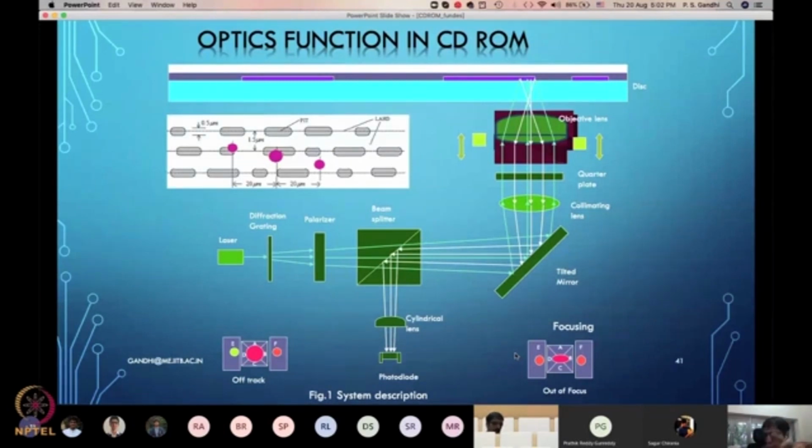Okay, this we often need to do in the practical world, when we are even configuring a simple motor and encoder system. Okay, what is the direction of encoder positive? That needs to match with the direction of positive force on the motor, or PWM positive, or whatever the direction of the motor positive is, that needs to get matched. They need to be mapped properly in the practical world, otherwise negative feedback will happen, and instead of stabilizing the system, it will destabilize the system. Okay, yeah.